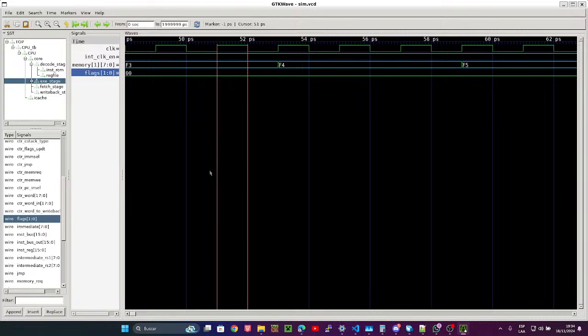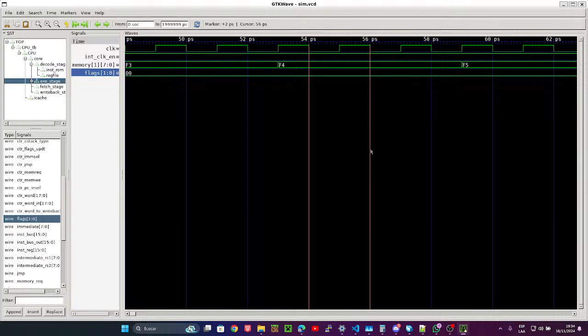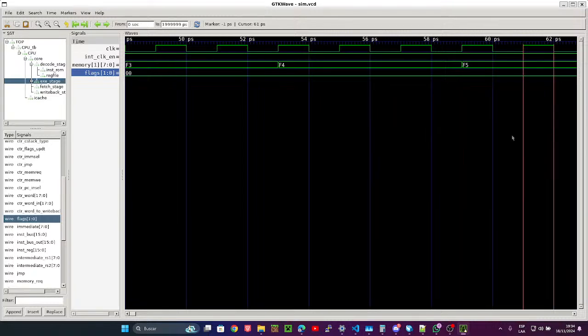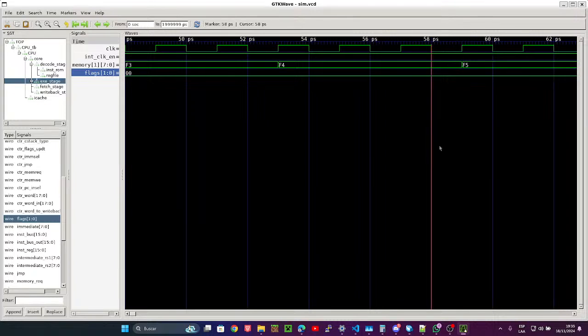That doesn't happen IRL because both 1 and 0 are active, and if you connect them, I'm gonna use another one of my quotes here. On the short term, it's called bus contention. On the long term, it's called hot chips, the crispy chips. It's like connecting a battery's plus to a battery's minus. You're gonna get heat. You're gonna burn whatever wire you connect the battery's ends with. I got another phrase.